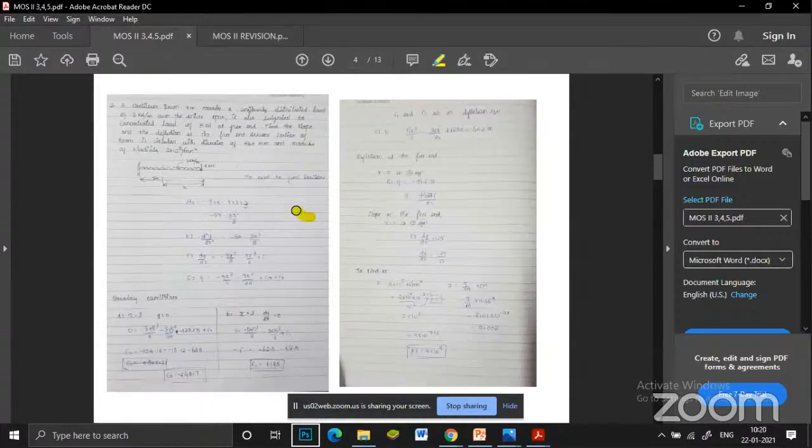First we have to find the moment. Why are we finding the moment? In a simply supported beam, we have to find the reaction and then the moment. Here there is no need for reaction because it is a cantilever beam, but you have to find the moment for this section. Then I have to integrate. We know how to find the moment; we have seen it in the last class. Then we have to integrate: moment, then slope, then deflection.